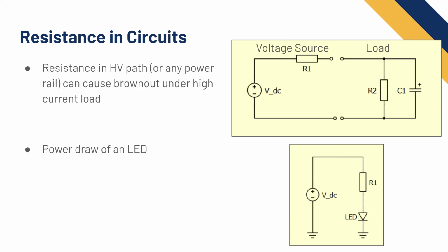Like that's not a lot, right? Real batteries, it's like milliohms, but I'm making my math easy. Let's say it's only 1 ohm, right? That's not a lot, that seems pretty small. But it's a 600 volt battery. And now let's say the load is our inverter, which is going to be pulling some current across the resistance and have some voltage on the capacitance.